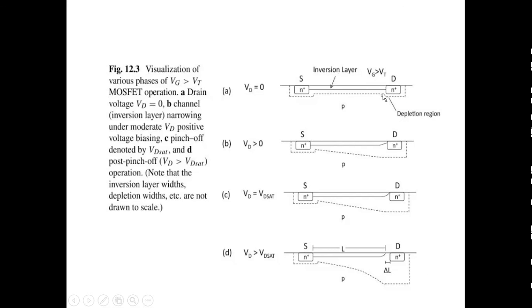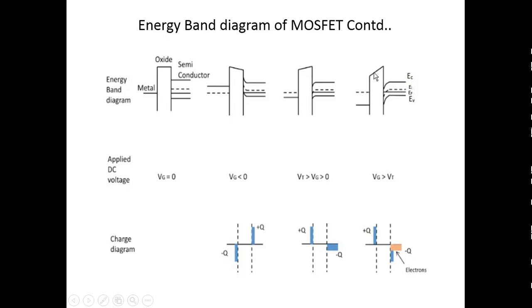When the device operates, the silicon band has been bent down. So here the intrinsic Fermi level and the new Fermi level differ due to this bending down when the device is operated. Of course, this is the new Fermi level shown here, and the actual Fermi level is just lower than the new Fermi level which is formed here.